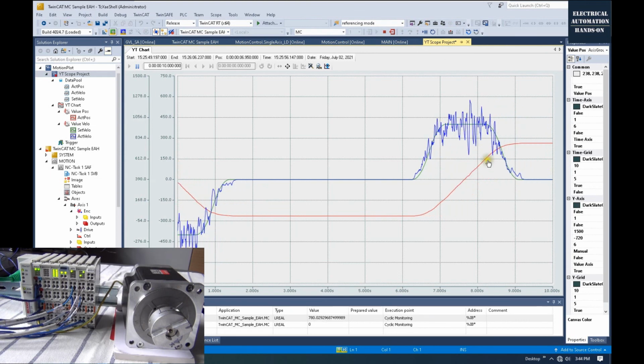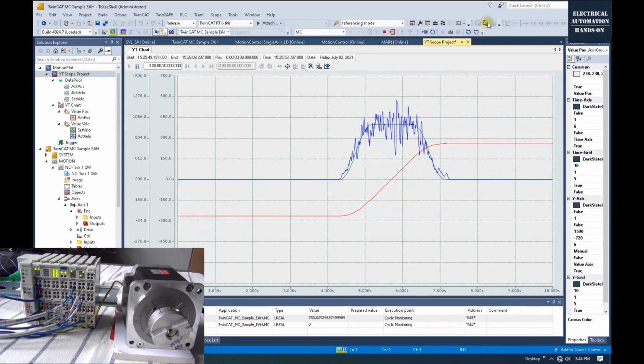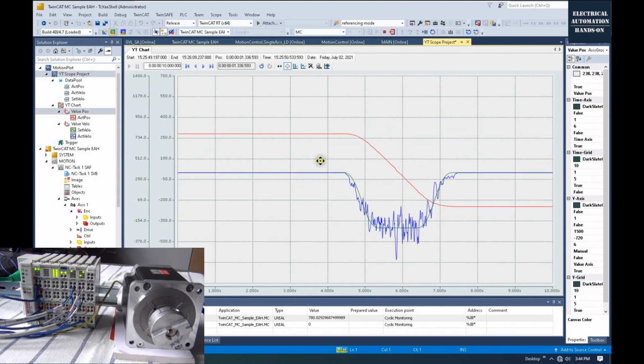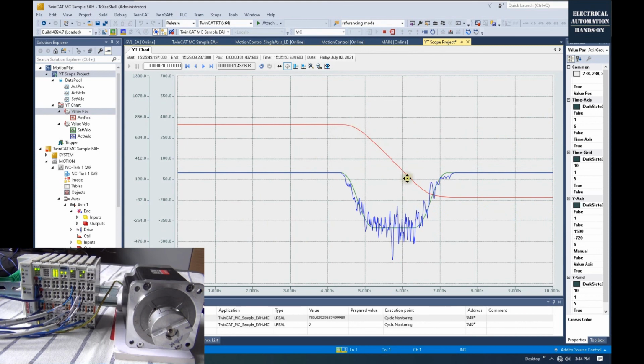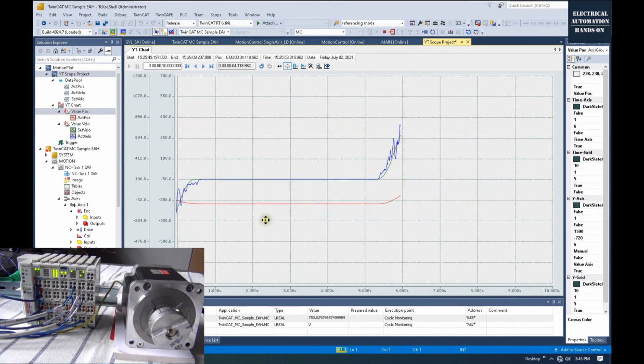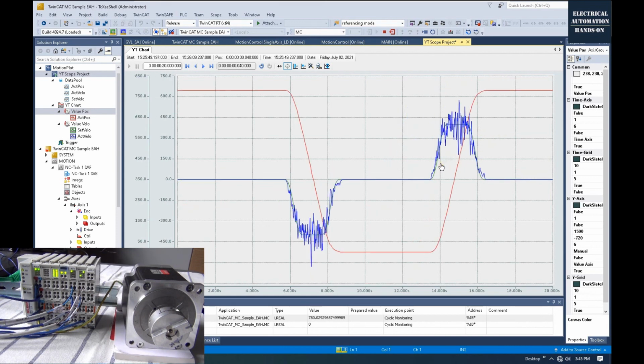So we can see this time the curve is much smoother than last time, right? I stop this recording. So we can see this curve. Now the K value for the standstill, which we increased from 1 to 5, makes it much better. So this curve is also a very convenient tool when we are optimizing this control loop for speed and precision.